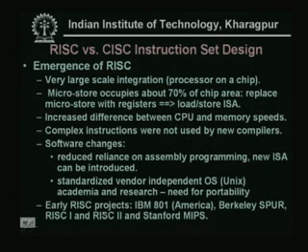So, if we summarize the instruction set design: for the advancement of VLSI, the chip can be of small size, and microstore occupies 70% of chip area. So, replace microstore with registers, the load store. So, more registers can be implemented. The difference between CPU and memory speed increases. Complex instructions were not used by new compilers, and software changes reduced reliance on assembly programming.